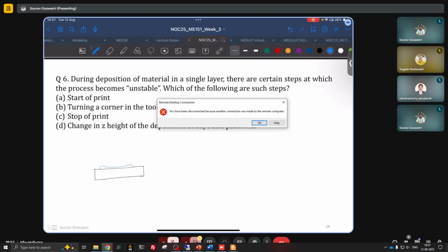There might also be certain processes where at the start of deposition there is under deposition, but mostly this region in the middle is steady state and has pretty uniform characteristics. Irrespective of whether it is under deposition or over, we can definitely say that the start of the print is a time of instability where the process is not really under our control, is rather unstable.